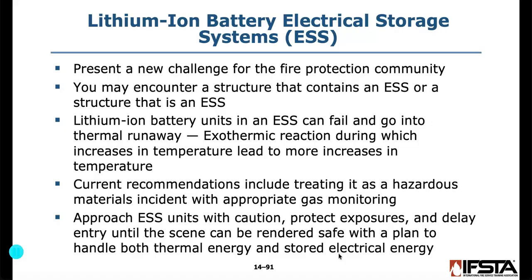So these present a new challenge for the fire protection community. You may encounter a structure that contains an ESS or a structure that is an ESS. Like I said, we have both, right? Lithium-ion battery units in an ESS can fail and go into what's called thermal runaway. Thermal runaway is essentially that exothermic reaction during which it increases in temperature and leads to more increases. These batteries are stored in banks, right? So this battery gets going, it goes into thermal runaway. You can put water on it, it'll cool it down, but once you take that water away, it goes back into thermal runaway and it heats right back up. Well, now it gets that next bank going, that next bank going, that next bank going.